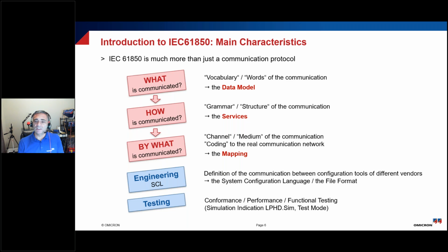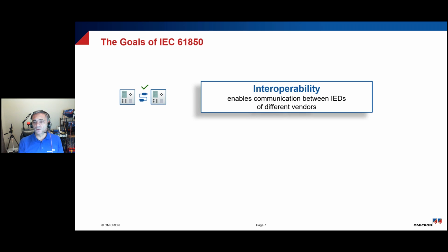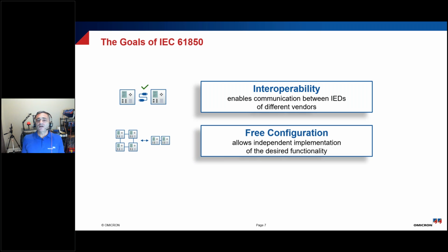So that's what it is: it's actually a group of standards, the IEC 61850 protocol suite. And the goal of this standard is to allow interoperability between devices from different vendors, and this helps out the utility greatly. Also, it allows for free configuration within the individual devices themselves, to be independent, but to be able to still have interoperability between the devices for this configuration.